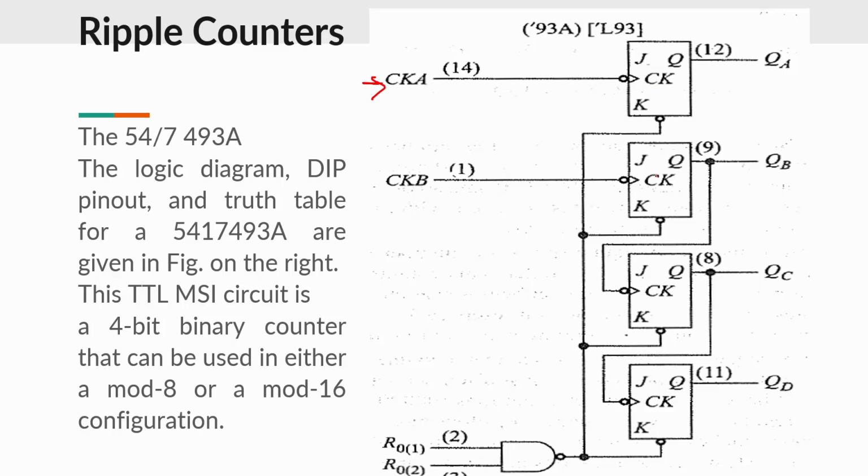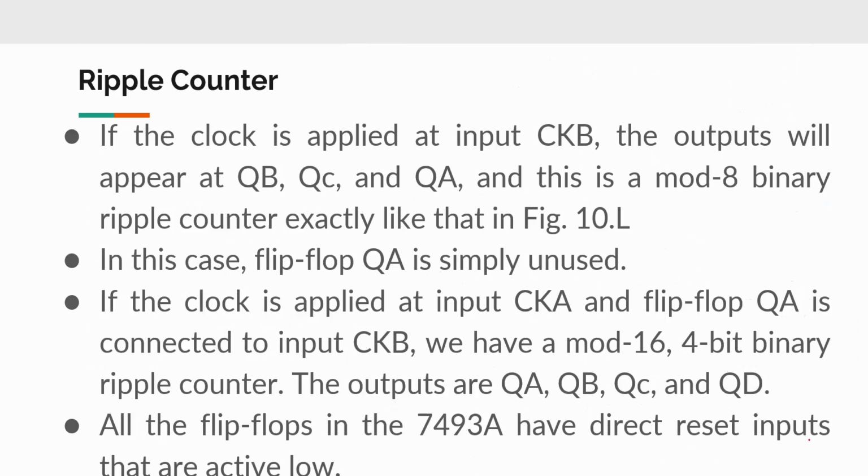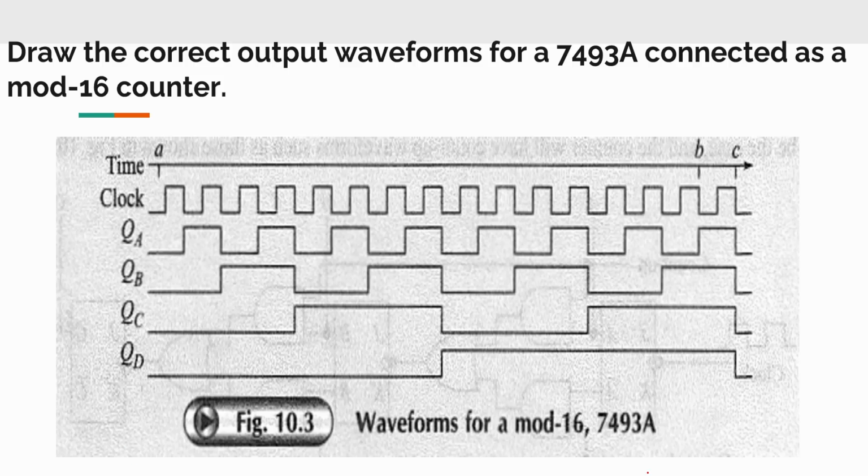All the 4 flip-flops are active in this state, and it will generate 4 different output patterns. 4 output pattern means 2 to the power 4. It will generate 16 different states. That means it will act in mode 16 asynchronous count fashion. This is again up counting. Okay, so this is the timing diagram corresponding to this particular IC or 4-bit up counting.